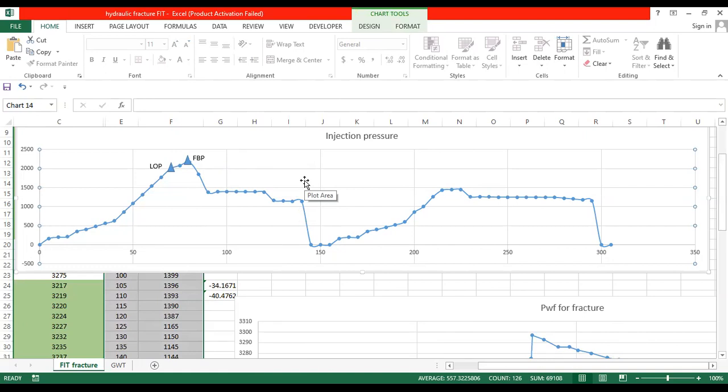So the fracture volume was more. Because of that, the pressure which was observed inside the fracture will start to get reduced until it attains a constant pressure. So this constant pressure indicates that, with that constant pressure, fluid can be flown through that fracture. Whatever amount of fluids we are injecting, that attains a constant pressure and it will start to move in that fracture with that constant pressure. So the starting of that constant pressure is fracture propagation pressure.